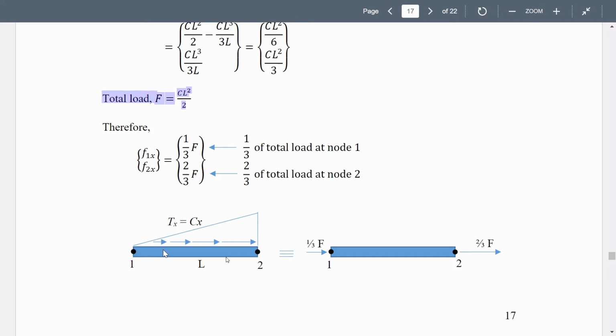In the seabed, we hammer these columns, these posts, and then we can put, for example, the harbor on this. So these poles that we insert into the seabed behave something like this. At the bottom, the force is very large, and at the top, it is very small. So actually, a behavior similar to this.